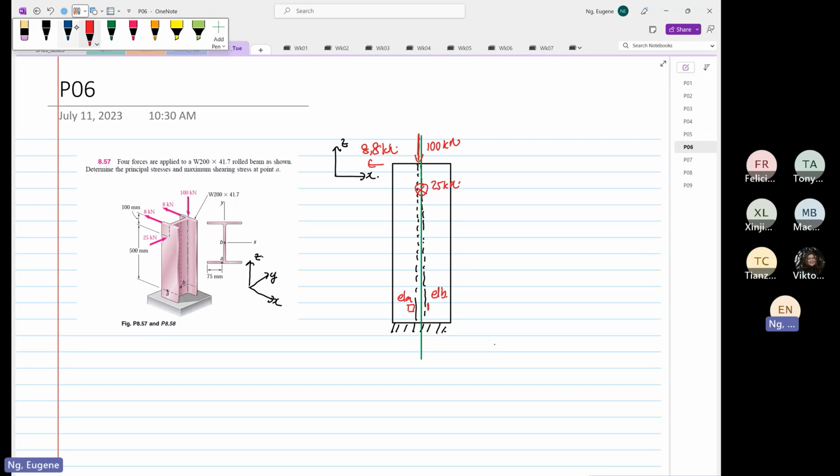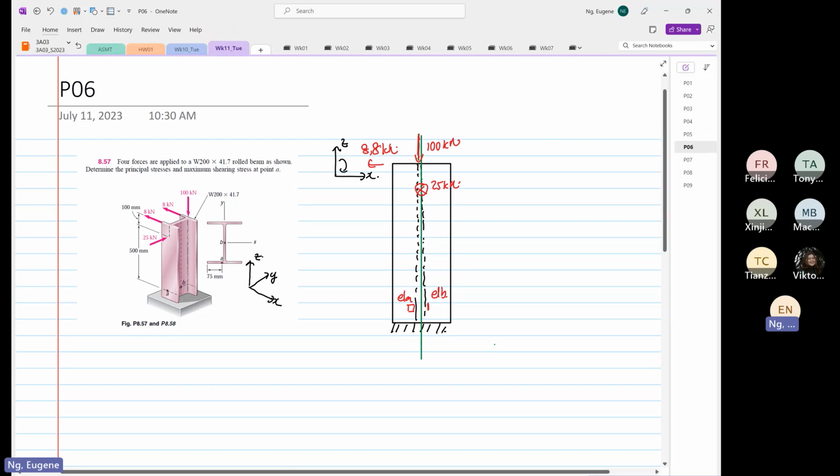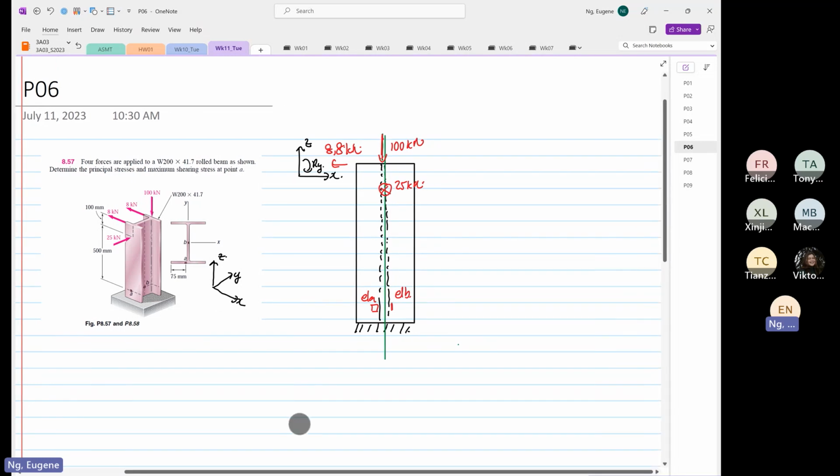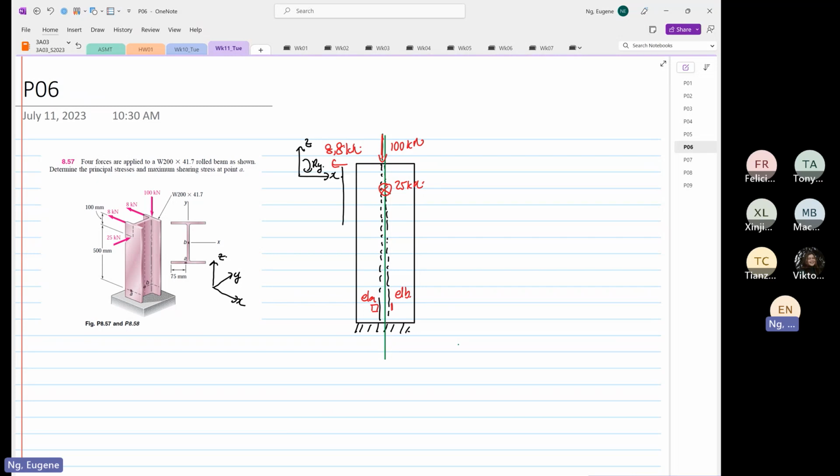And then we are going to draw our rotation in Y. So we know from here that we have a moment about Y due to the 8 kilonewton, twice 8 kilonewton, and it's perpendicular to the centroid. So your distance to take is the distance to the element, and that distance is equal to 0.6 meters. I'm going to call anti-clockwise as positive now.